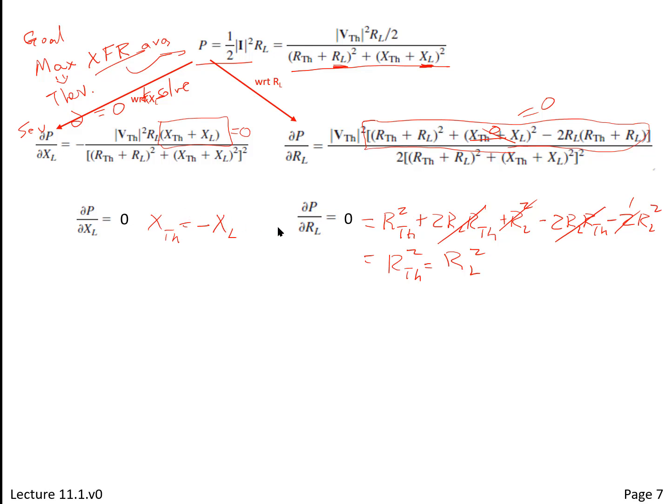And we get that for maximum power transfer, R Thevenin is equal to RL, which is sort of like what we knew intuitively just from the basic Thevenin equations if it was only a real load. So maximum average power happens when we're able to basically get rid of the reactive part and end up with a strictly real part in the Thevenin sense, just like DC.